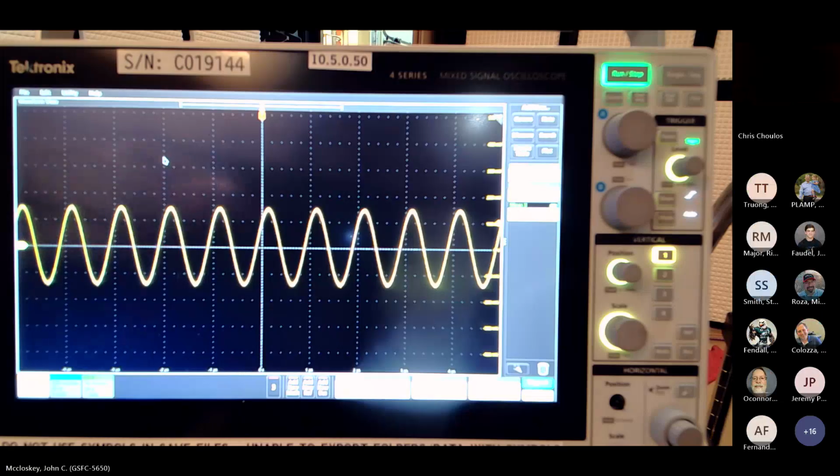Okay. So the reason I'm showing you this before we even inject into the probe is that with any RF signal generator with a 50 ohm source impedance, the level that it's telling you, this 100 dBµV, which equates to 100 millivolts RMS, which is what we're seeing here, assumes you've got a 50 ohm load on there. It's got a 50 ohm source impedance, and it's telling you this is what I'm going to give you into a 50 ohm load.